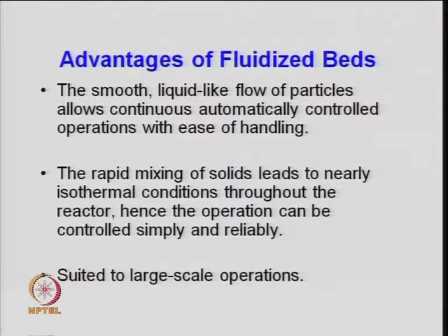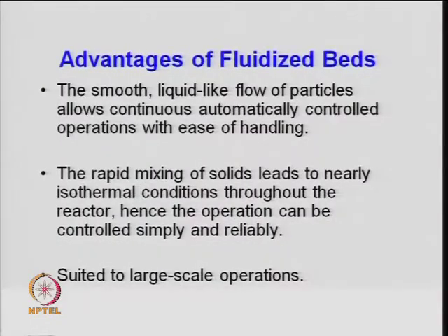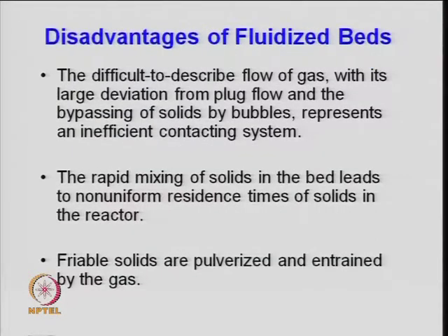And again, I told you that solids are moving up and down in this, right. They are going up and they are going down. So, there is a kind of internal circulation, so there will be good back mixing in this reactor, right. So, rapid mixing of solids leads to nearly isothermal conditions. So, where heat transfer is an issue, the fluidized bed reactor may be helpful, right. Throughout the reactor you will have good control of heat, and hence the operation can be controlled simply and reliably, right. And these kinds of operations can be done at large scale, but there are disadvantages also, right.